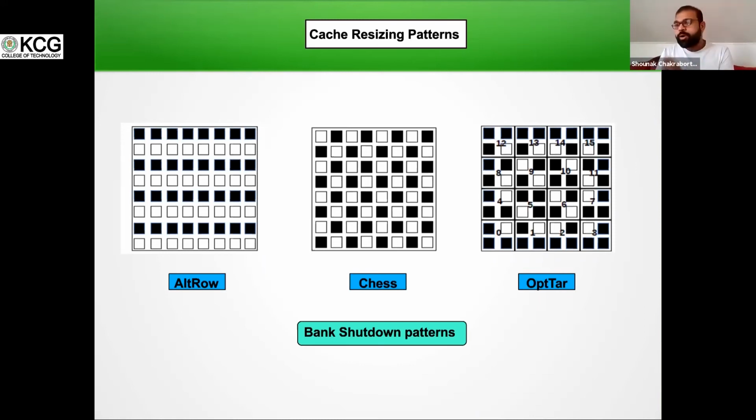So that's the concept here, and why have we turned off all the banks at the periphery? The idea is that our hotspots are on the cores of the chip. The cores were at the periphery in this baseline architecture. So if we can turn off all the peripheral banks, they will generate a thermal buffer close to the cores. Thus, the cores' peak temperature will be reduced. That was the primary idea for this scheme.